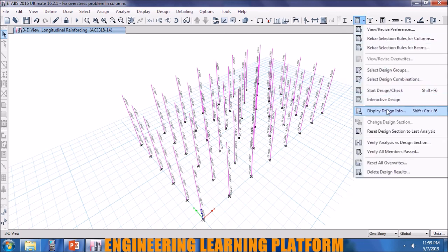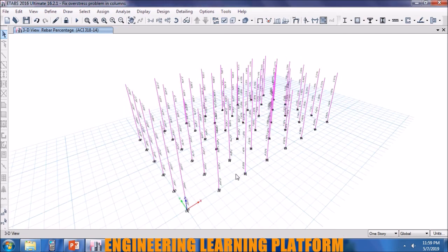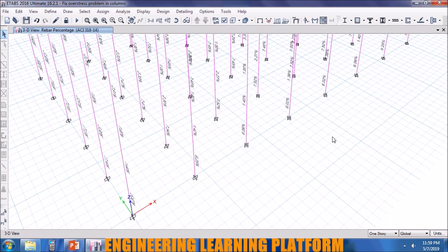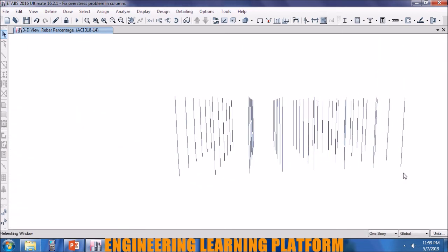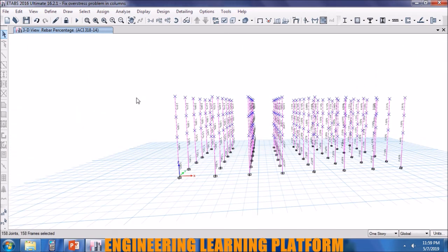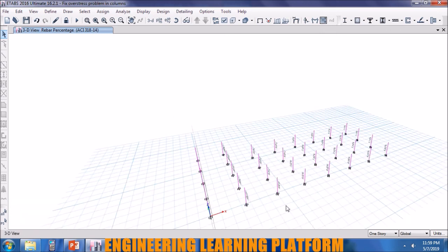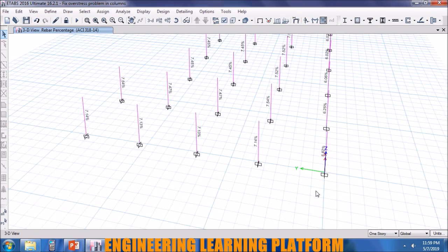It is also important to check whether the reinforcing percentage is not high enough so that it's practically not placeable in the column. You see the percentage here is 7, which is very high. Practically we want to be able to apply that particular percentage of steel. You have to see the percentage of steel for one story at a time.